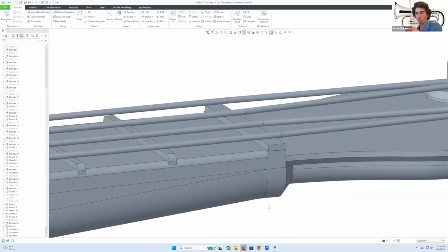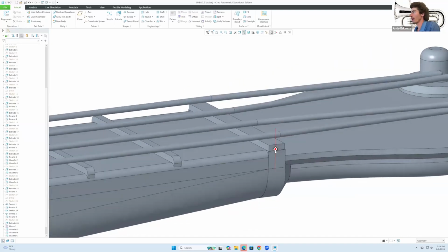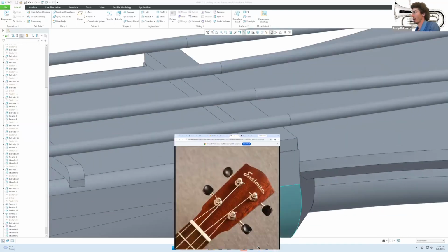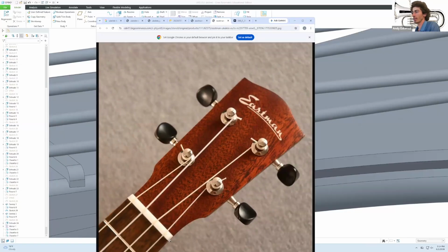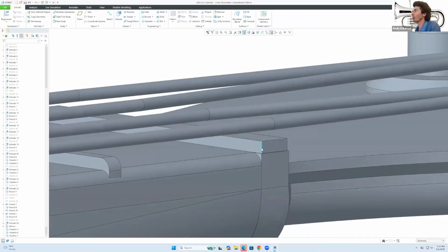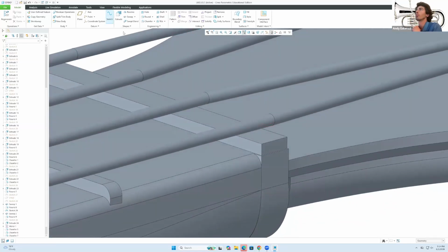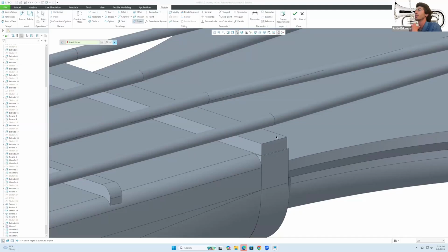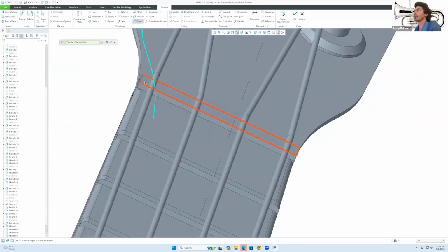Almost done here because the next piece that we're going to modify is this block over here. So for that, we're going to look at how that is supposed to be structured. And you'll see that the strings are not supposed to be floating, but rather they should be a little bit high up. So what we can do is go here to sketch, over to that face, and I can just project all of these lines right there, click on OK.